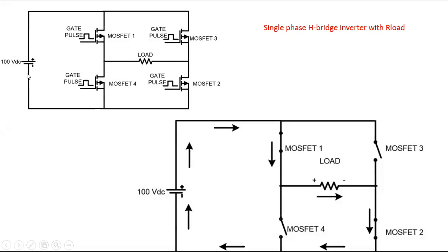You can ask one question: sir, can we use the SCR in the inverter? Anyone tell me, can I use the SCR in inverter? No, the answer is no, because to turn off the SCR we require complicated circuits, but MOSFETs can be easily turned off. Okay. So maximum inverters will never have the SCR, they go with the MOSFET only. That's why here also MOSFET: source, drain, gate. From an examination point of view, you can draw the SCR also. This is one more animation.